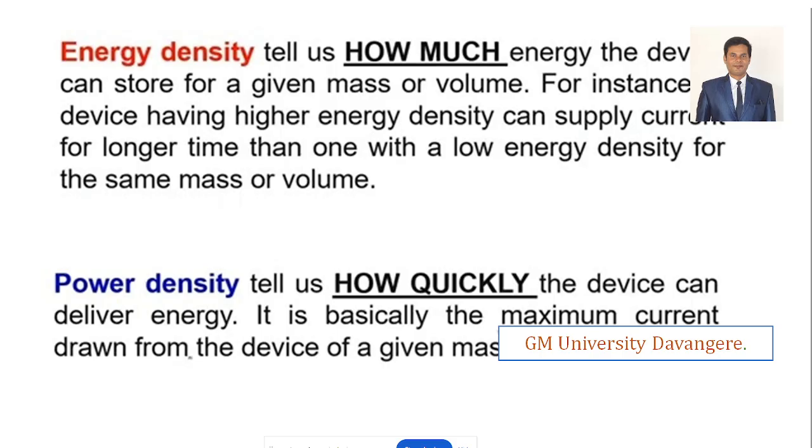So, with respect to the capacitor, the capacitor will respond very quickly. That's why we use it in power grids, for making the grid stable. We use switching for reactive power compensation in the transmission lines, where we can use ultracapacitors for the switching of the power devices, to give reactive power from the capacitor bank back to the transmission line, so as to maintain the stability of the reactive power, right? So in those cases, we are using power densities, especially in grids, right?